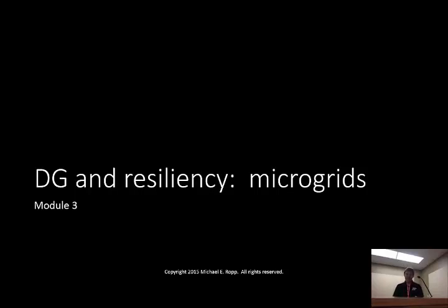We have seen some cases where they tend to run on more readily than strictly inverter-based units, because the positive feedback anti-islanding is trying to move the VARs in one direction or the other, while the transient VAR demand of the machine tends to go in the opposite direction. We see this a lot with the self-excited machines, but it can be self-defeating if you're not careful. So I don't have the same numerical guidelines for you on a Type 3 wind turbine, and I apologize for that, but they would be wider than would be the case with a strictly inverter interface source.